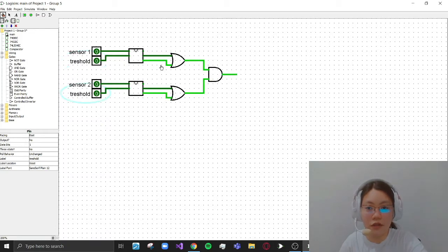And that is the definition of the condition where sensor 1 and sensor 2 are only greater than or equal to the threshold. So if all of them are turned on, then the signal will be on because they are still equal. The same goes for when they are all turned off, and also when sensor 1 is greater. So we have proven that sensor 1 is greater over here because we have used the comparator, the simple 1-bit magnitude comparator. So this concludes my part for project 1, and the next presenter will be Sienna once again for the other component.